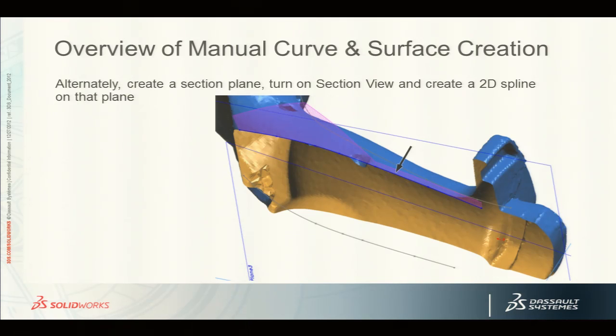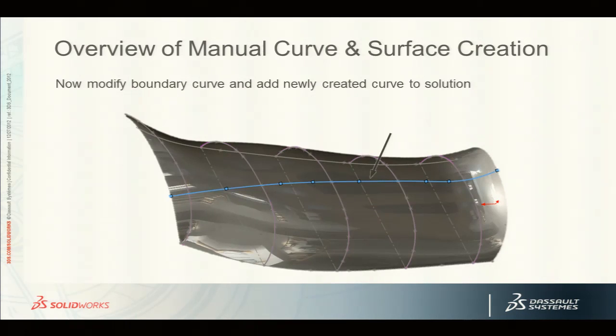So I'm using the coolness of snapping to the mesh, but in the same way, I'm also adjusting it to be a very smooth curve. So you use the best of both. So now, because in SolidWorks, you don't delete anything, you don't trash anything, you modify everything, what I've done is I've rolled back, I've created a new curve, and now I'm going to edit the boundary surface and include that curve. So what I'm doing is I'm reiteratively making my boundary surface more and more accurate by adding new curves to it. And that's what I've done here.